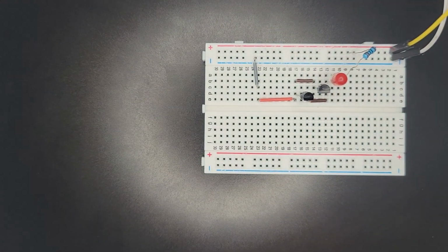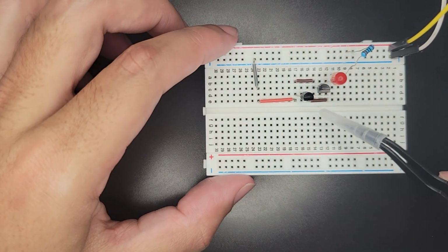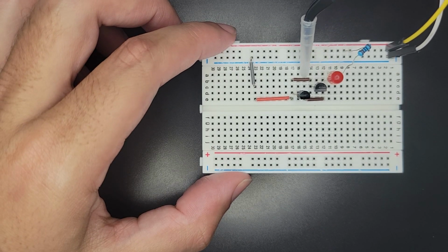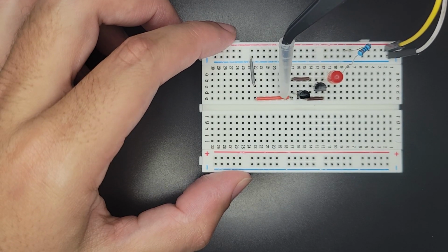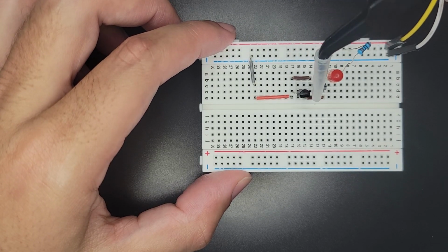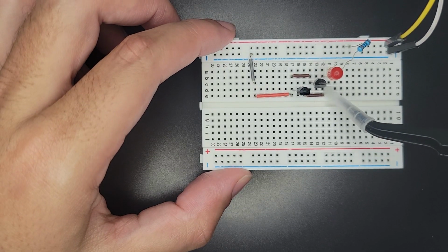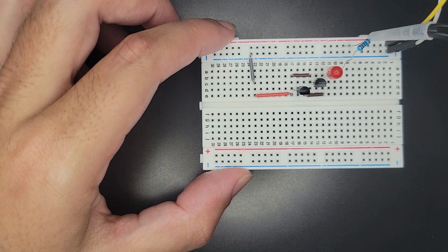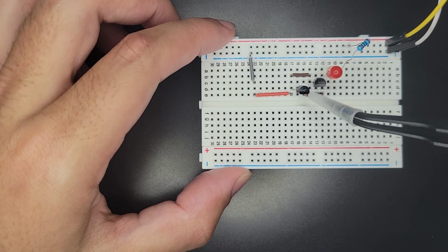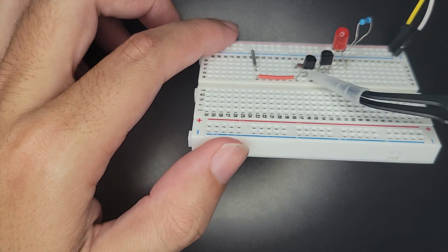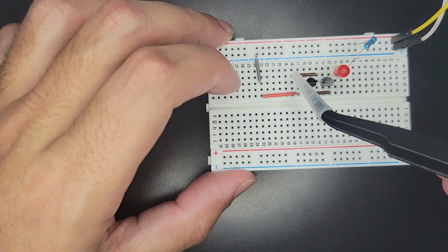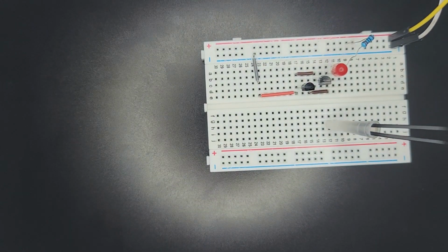So what we have now is power comes in, goes in the LED, goes to both collectors, and A's emitter outputs from 14 to 17, where it joins this cable and goes out to ground. Transistor B takes power from the brown cable, right, coming from the LED. So power LED on 11 into the brown cable. Transistor B gets it in the collector, and then it can output onto row 17. So everything pretty much goes to row 17.